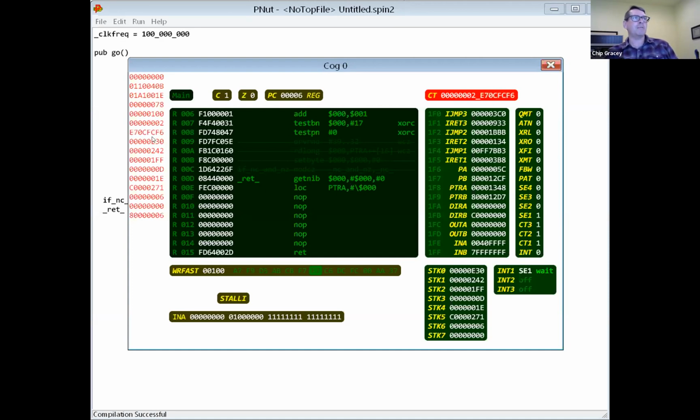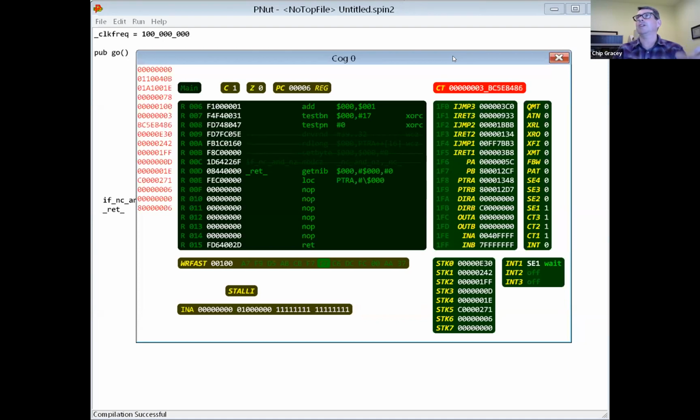So as these new messages come in, you can see, can you see my mouse cursor? Okay, these are the count values here. Here's count low, count high up here. So it just resends the current packet without having stepped anything. And that way you can run normal debug messages between this thing spitting out its, hey, what have you got for me? Or have you got a button press yet? So in the background, you can run all your normal debug displays. You can run up to all 8 of these things, and they all play together without anyone pulling the rug out from anyone else.